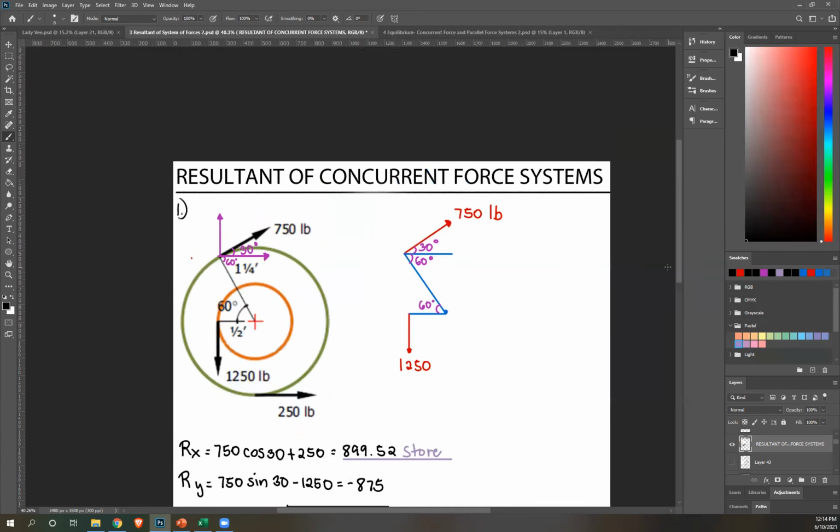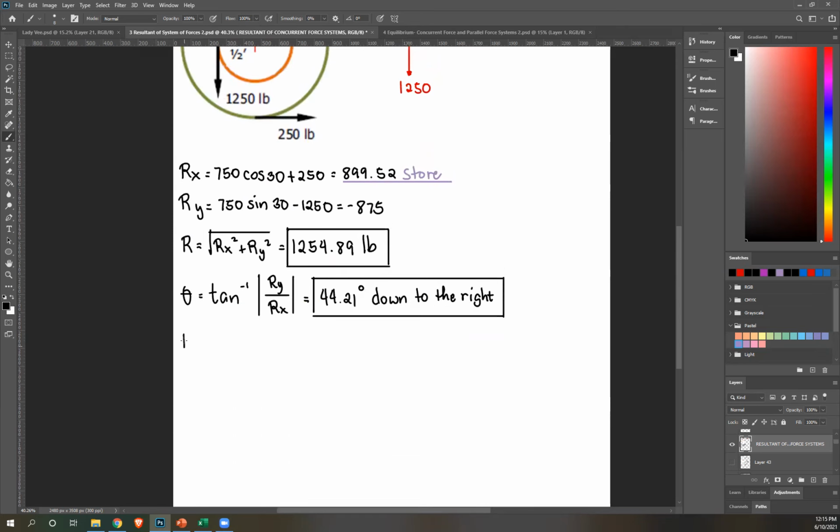Okay. So since there's no support here, this is just a pulley. So usually our reference point is the center. Okay. So center, let's take moment about center. Let's call that MC. And recall the equation MC equals RD. For summation of MC equals RD. Okay, let's begin. MC, again, that's force times distance.